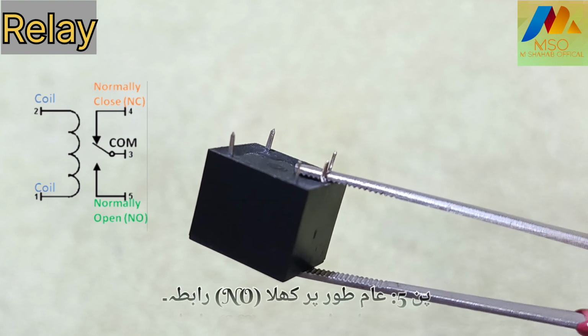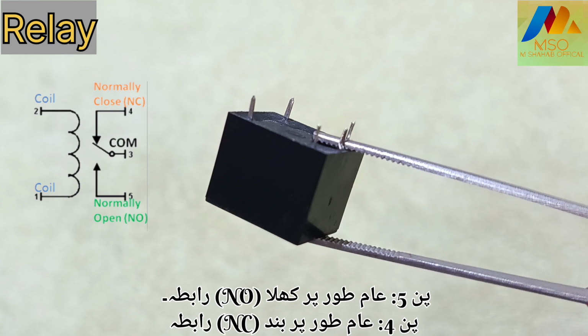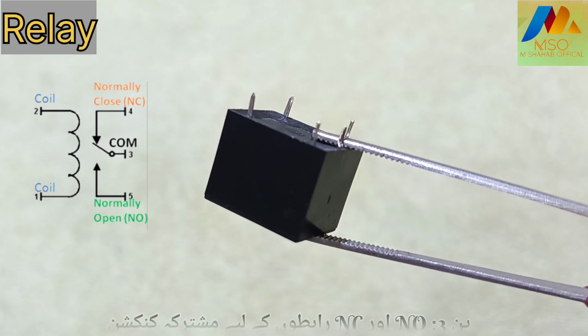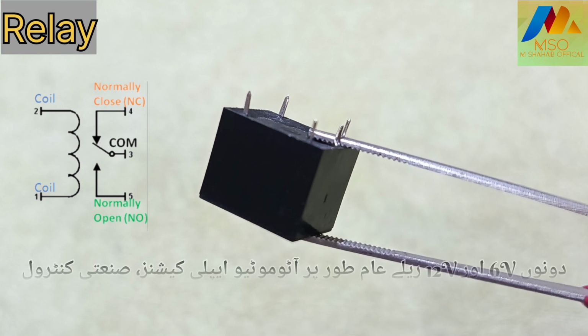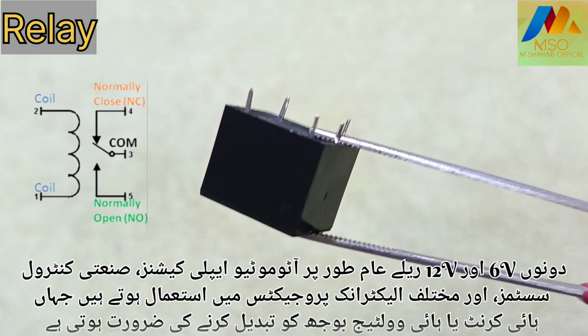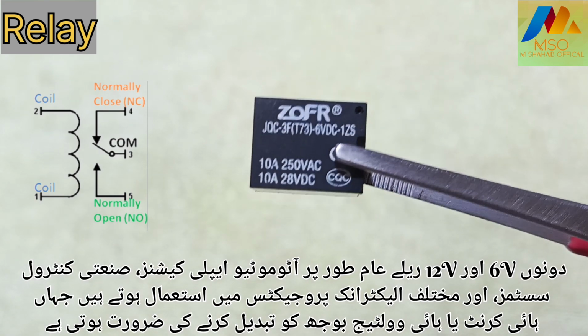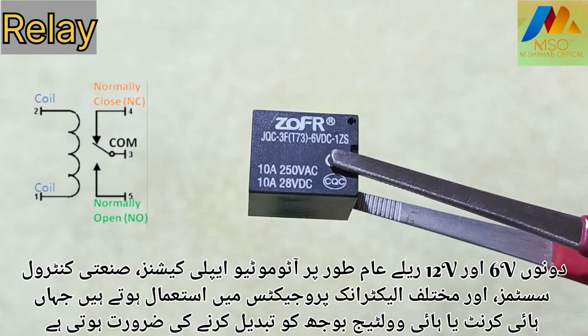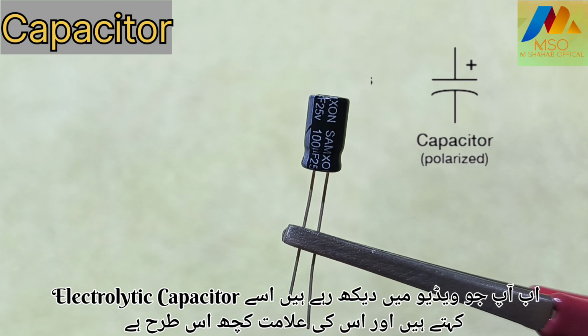Pin 5, normally open, NO, contact. Pin 4, normally closed, NC, contact. Pin 3, common connection for the NO and NC contacts. Both 6V and 12V relays are commonly used in automotive applications, industrial control systems, and various electronic projects where switching high current or high voltage loads is required. Now what you see in the video is called an electrolytic capacitor and its symbol is something like this.